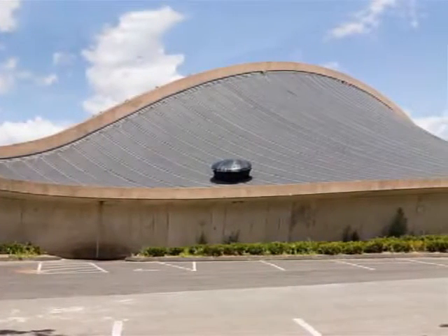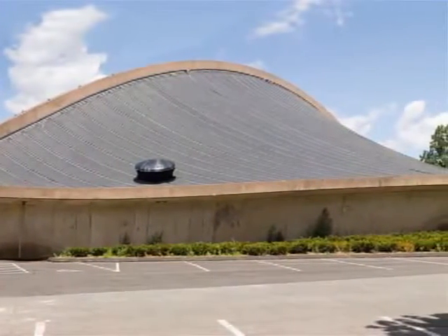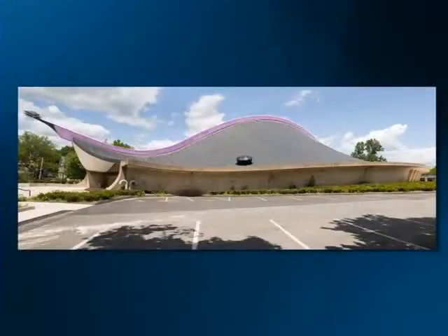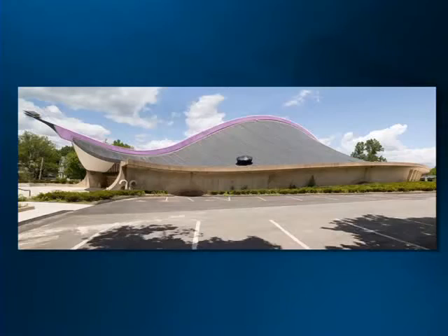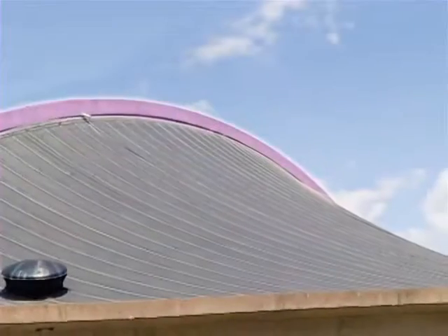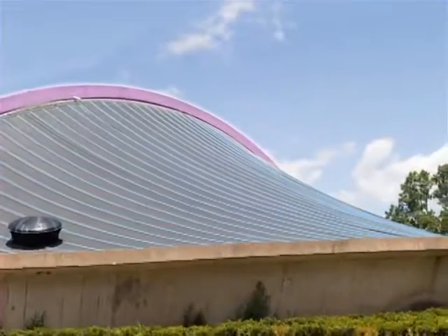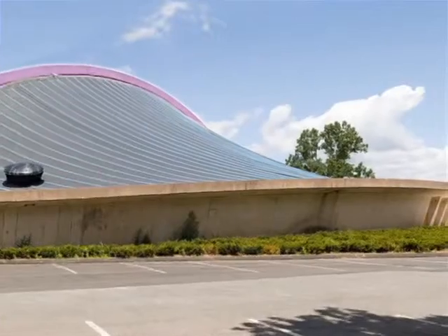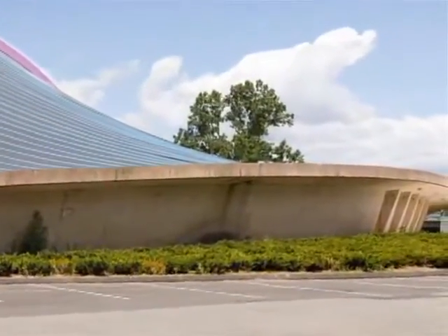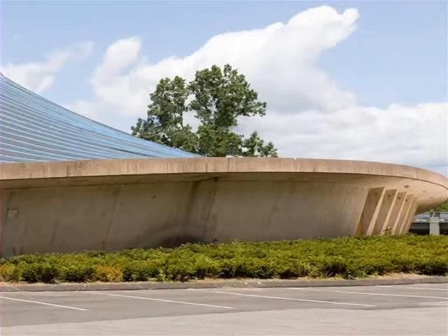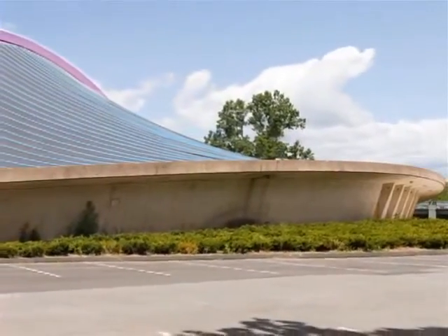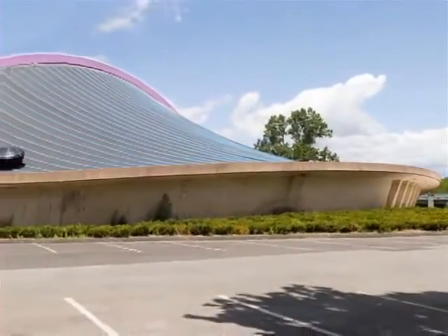Begun the year after the Dorton Arena was completed, the Ingalls hockey rink has a completely different physical appearance, but it actually uses a very similar structural concept. That gracefully curved central spine running down the center of the roof is actually a reinforced concrete arch, nearly 300 feet long. Steel cables are then strung from the top of this arch outward in both directions, and they're anchored at the top of the building's curved walls. The inward pull of these cables is counterbalanced by the curved walls, acting very much like arches turned sideways. The steel cables then support a timber roof, and it's actually the weight of that roof that gives the cables their curved shape.